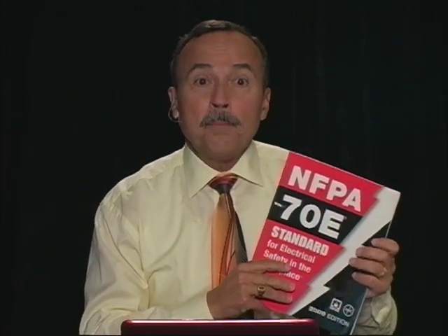There is no voltage. Now you can take your suit off. Now you can work on it. You are not supposed to say, oh, I need to have an 8 calorie, so let me go get an 8 calorie and put that on there. And now let me go ahead and remove the breaker and replace the breaker in an enclosure. You cannot work on anything hot, period, ever.